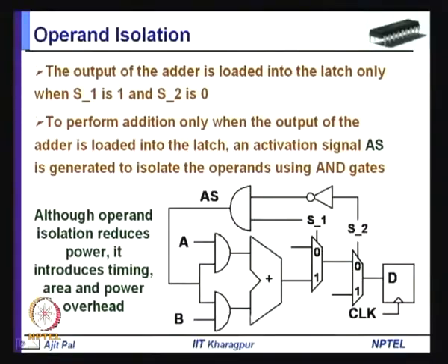So, you have to find this condition using very simple hardware, so that this trade-off is satisfied, and obviously you are adding some additional area to achieve reduction in power dissipation. So, you are trading area for lower power by reducing the switching activity. So, this is the technique of operand isolation.